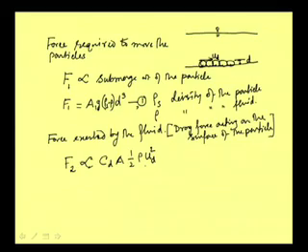Again, what should be this d? There is a lot of controversy, as we say that d is the average particle size. Now, in a real situation in a river bed, particles will be of different sizes, and if we carry out a sieve analysis, we will find that gradations are different, so which value will we take?